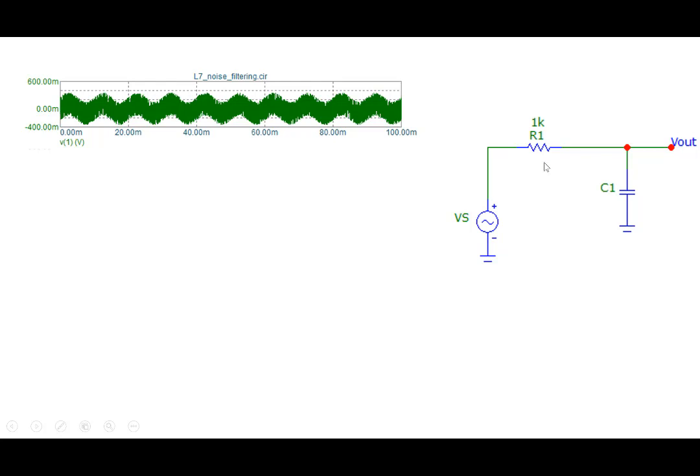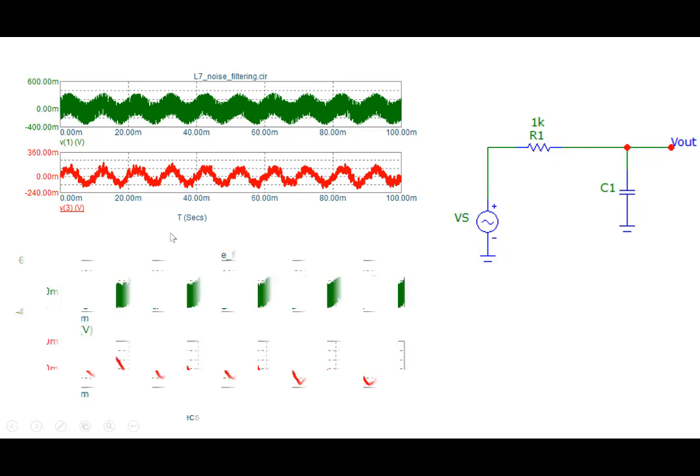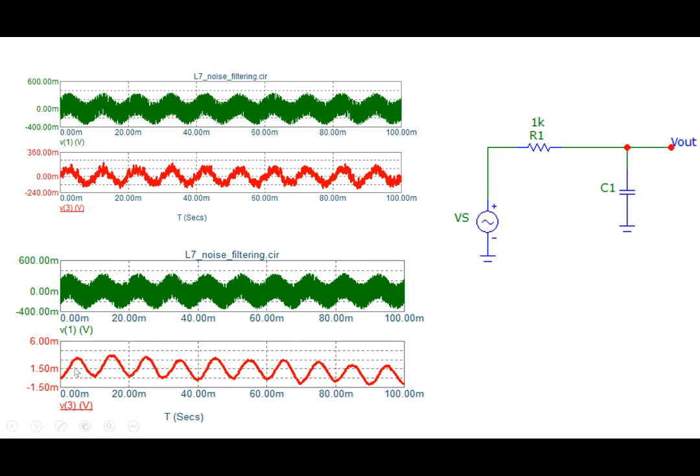And look at what this simple circuit is able to do. Right? It's able to reject noise to a large extent, and now you can see the sinusoid which is there here. Even now it's still noisy. Still you can see that, yes, you can see the periodic signal, you can measure its frequency. You could tell maybe what its magnitude is going to be, but you could filter it even better. So if you understand how this simple RC circuit works, you could adjust the values of R and C and filter it better. So let me show you a better filtering. See, with the proper choice here, now you can see that the sinusoid is much cleaner.